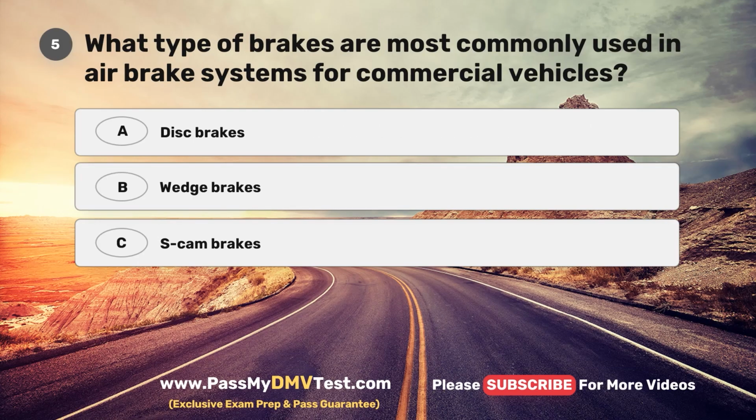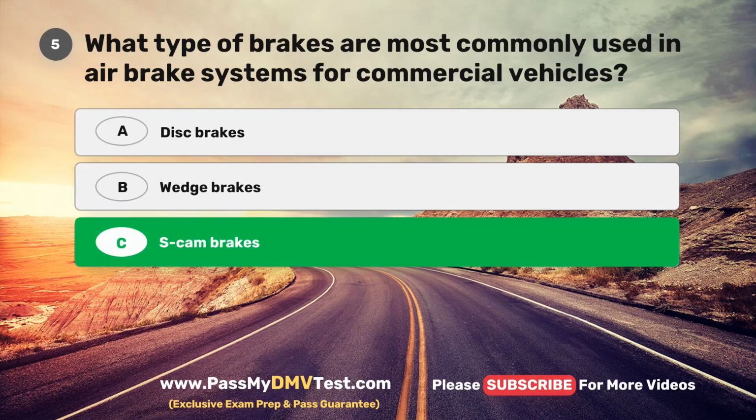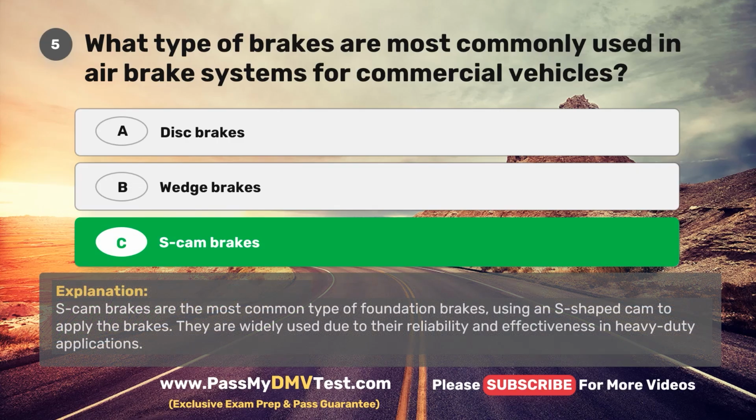Question 5. What type of brakes are most commonly used in air brake systems for commercial vehicles? A. Disc brakes. B. Wedge brakes. C. S-cam brakes. The correct answer is C. S-cam brakes. S-cam brakes are the most common type of foundation brakes, using an S-shaped cam to apply the brakes. They are widely used due to their reliability and effectiveness in heavy-duty applications.